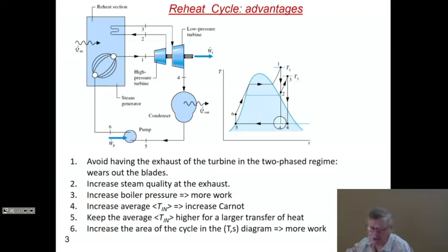And so these droplets of water that impact the blades erode the blades and create wear on the turbine. You really want your turbines to work as much as possible on high quality steam. And in fact, that is the reason why this X fraction is called quality. It's because the higher the quality of the steam, the less damage it does on your machines. So this is a quality of 1, and you want the quality to be as high as possible to decrease this problem.